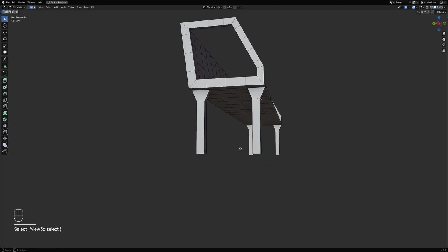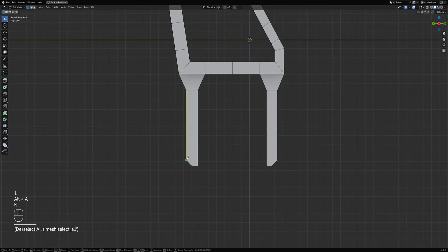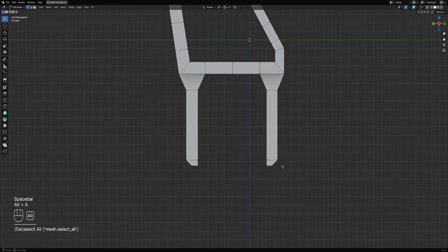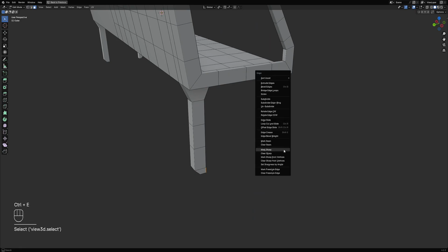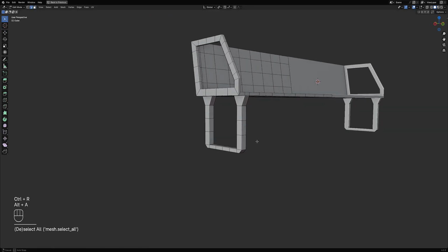Connecting this one and this one. Press K for knife, and then use this vert here, and then A to snap it to angles, and then press C to make the knife cut through the mesh, and click. Okay. Add two edges here as well, and Control E, bridge edge loop, and add additional topology here as well.